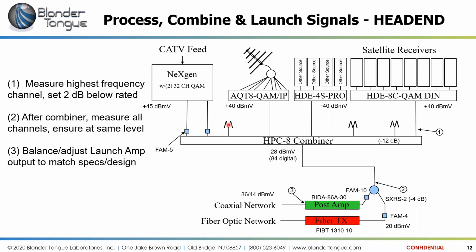What would be done to troubleshoot one port channel in the middle of the low-high frequency range if the channel of issue is good in the head end, but at the end of the run drops? The channels around it are of adequate levels and clean. Well, that goes back to the 200 to 300 megahertz range question, where it almost sounds like you have a suck out or a trap that's physically pulling out one or a group of frequencies. Again, I'll answer that one in email.